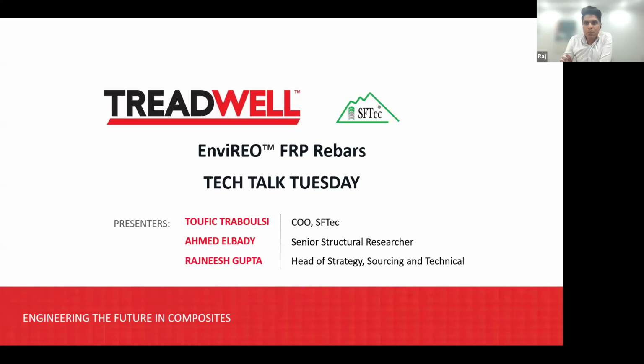So one of the reasons people ask about FRP rebars is, what's the advantage? Now, I like to start this with a problem. Given the topographical, geographical location of Australia or other countries which is susceptible to moisture, water, the structures are faced with corrosion problems that basically reduce its design life, because the corrosion in the rebars or the reinforcement makes it less usable over a period of time.